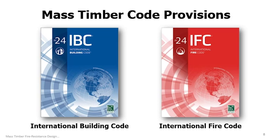The reason I'm basing this presentation on the most recent I-codes instead of an earlier version is because the new mass timber construction types were newly introduced in the 2021 edition of the I-code family. Earlier code editions recognized heavy timber construction, which was previously known as Type 4. It was just Type 4 because that was before the other Type 4 construction types were introduced. But these earlier I-code editions did not include the three new mass timber construction types that we'll be talking about here.